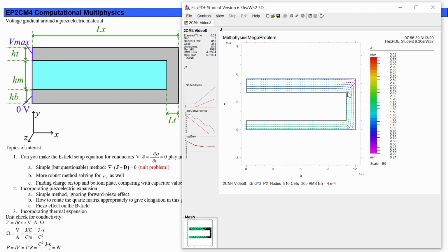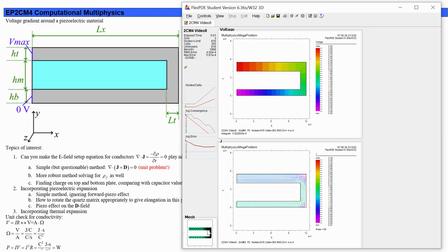I mean, the vector plot still might look kind of spiky because it's got a uniformly spaced set of vectors. So the density of the arrows here doesn't correspond to the actual grid density that's being simulated. You can see in some places over here it's got a lot denser arrows than is actually being simulated, whereas over here it seems like the arrows are less dense than what's actually being simulated.